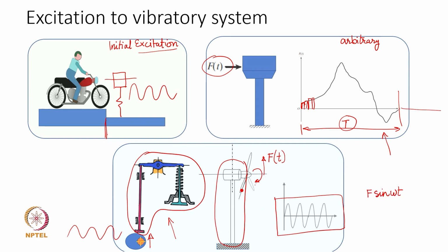So, if this bladed rotor spins at a speed of, let us say, omega radians per second, because we know that the unbalance rotates with the same frequency as the rotation frequency, and therefore, it varies harmonically with the same frequency omega as the rotational frequency. And here F, as you all know, is given by m e omega square, the unbalance force. So, the excitation force F, whose magnitude is this, fluctuates with the frequency omega, which is the rotational frequency in this particular case.